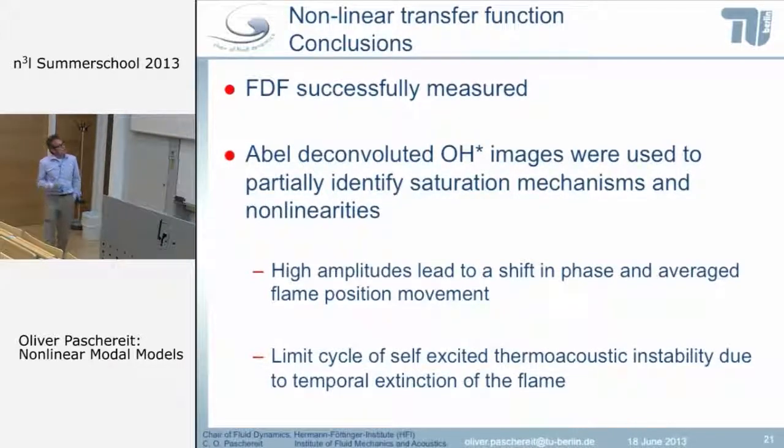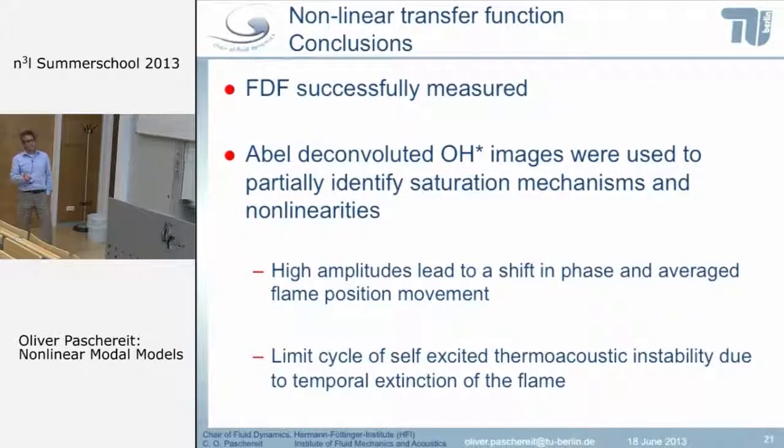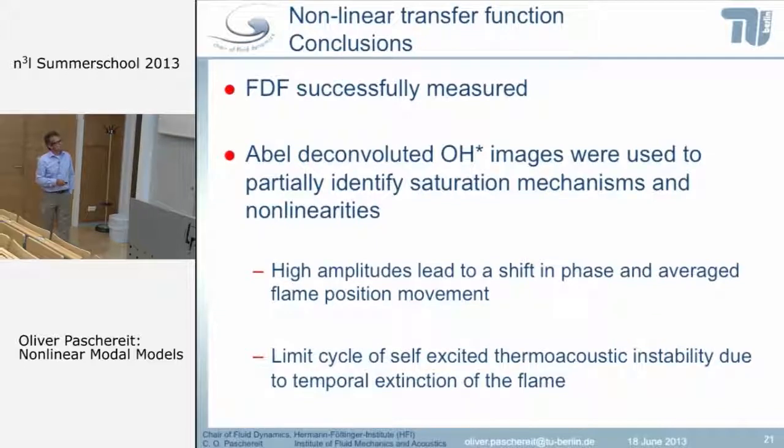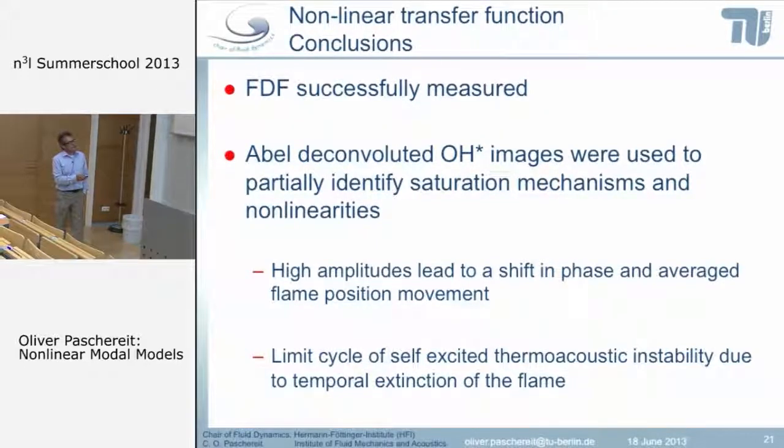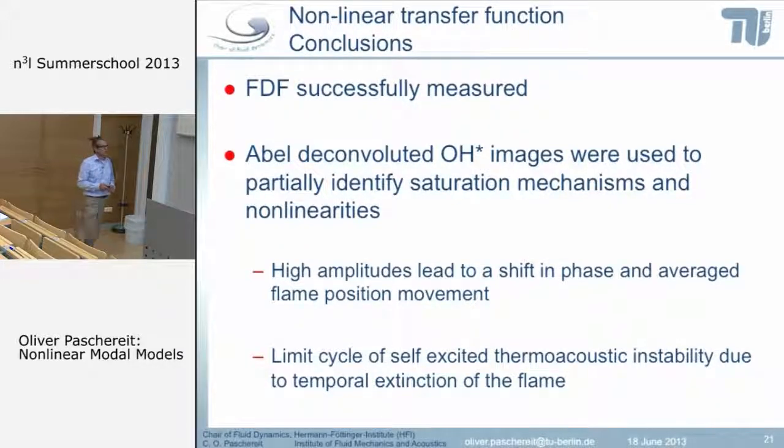And this is actually also then the conclusion for this specific case we looked into. We saw that the high amplitudes led to a shift in phase and average flame position movement, and the limit cycle in this specific case was due to a temporal extinction of the flame.